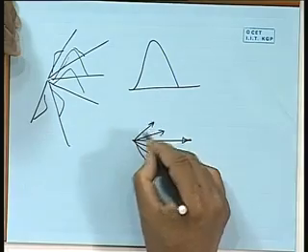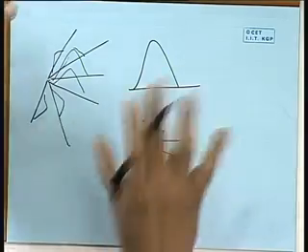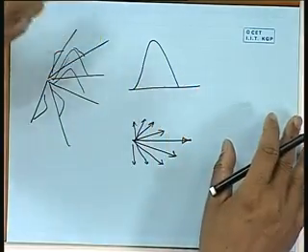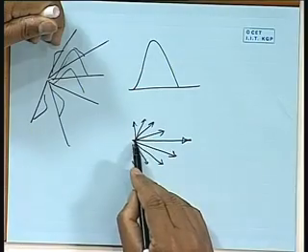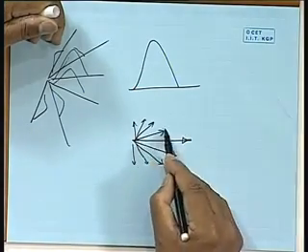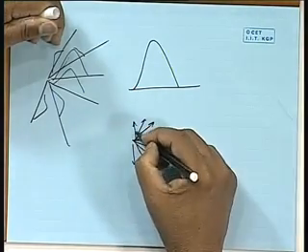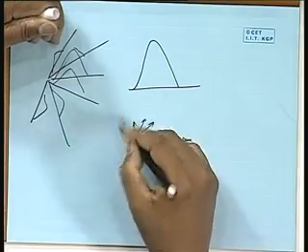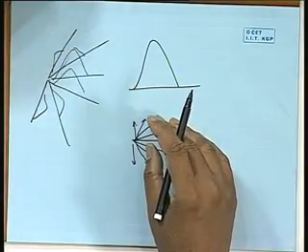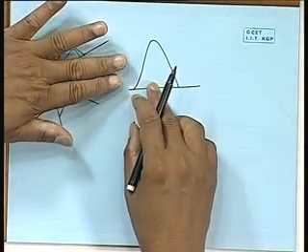That means you are assuming that the wave height or elevation that you are getting is because of the sum of all waves coming not only from one direction of all lengths but also from all directions, but the directional spreading gets thinned down. In other words, there will be much larger waves coming this side, a little smaller this side, a little smaller this side, and ultimately no waves this side. And this was simulated by multiplying this with a spreading function.